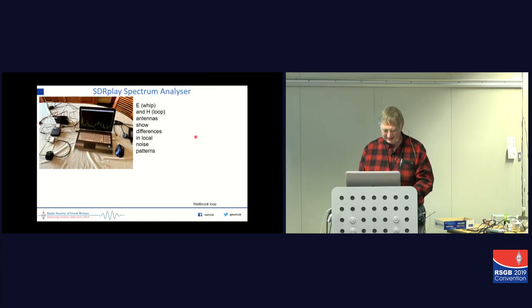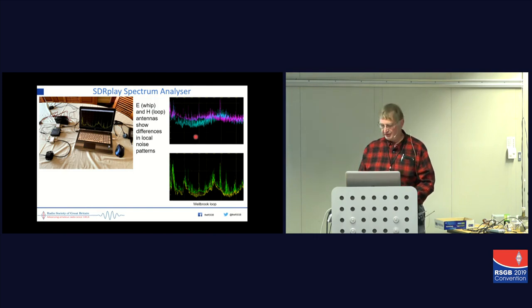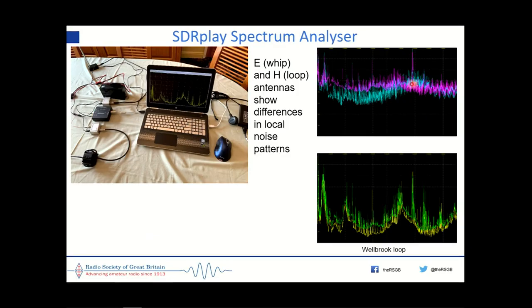And this has just gone blank on me. And this gives you some idea of what you can see. So this is an E-field probe taken near to this computer. With the power supply turned off is the blue line, and with it turned on is the purple line.